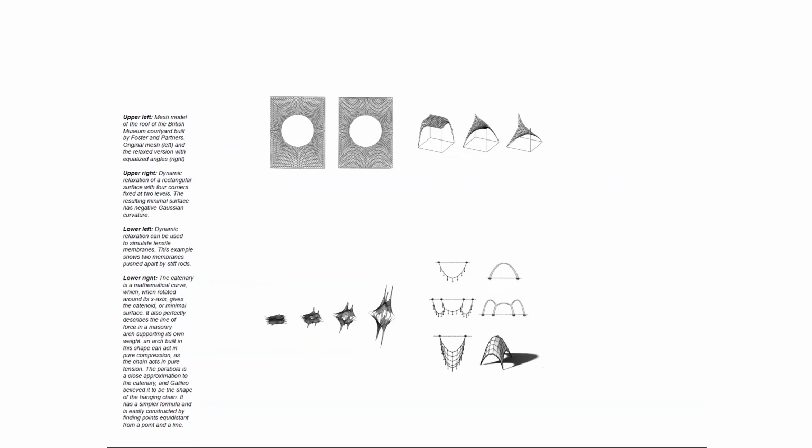The forces are tensile forces, and when you flip that, you get only compression forces. Okay, and this is how compression-only vaults in masonry are constructed. So look at Antonio Gaudi. He used this technique directly to compute the vaults in Sagrada Familia in Barcelona, but this was used since then. I mean, these principles were used in Gothic cathedrals as well, directly or indirectly.